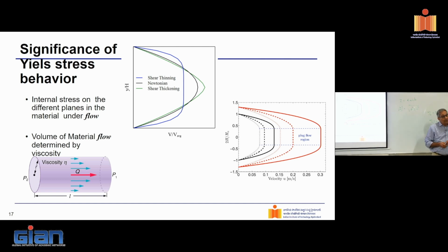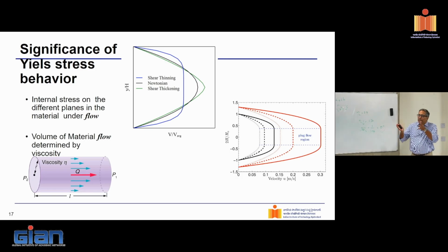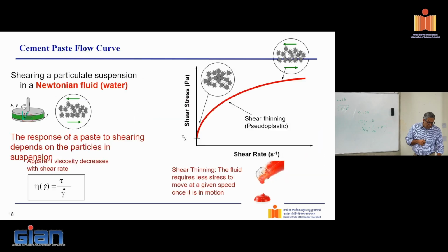Okay. So in a manner of speaking, this actually perhaps helps with the conduction or pushing the material through the pipe, because I'm able to develop this plug here. And there are mathematical theories that allow us to predict it. Now, cement paste has one more complication. So if you look at this graph here, how did this change compared to the Bingham plastic fluid? If you look at this here, shear stress versus shear rate, except in Bingham plastic, this was a straight line. What is happening here?